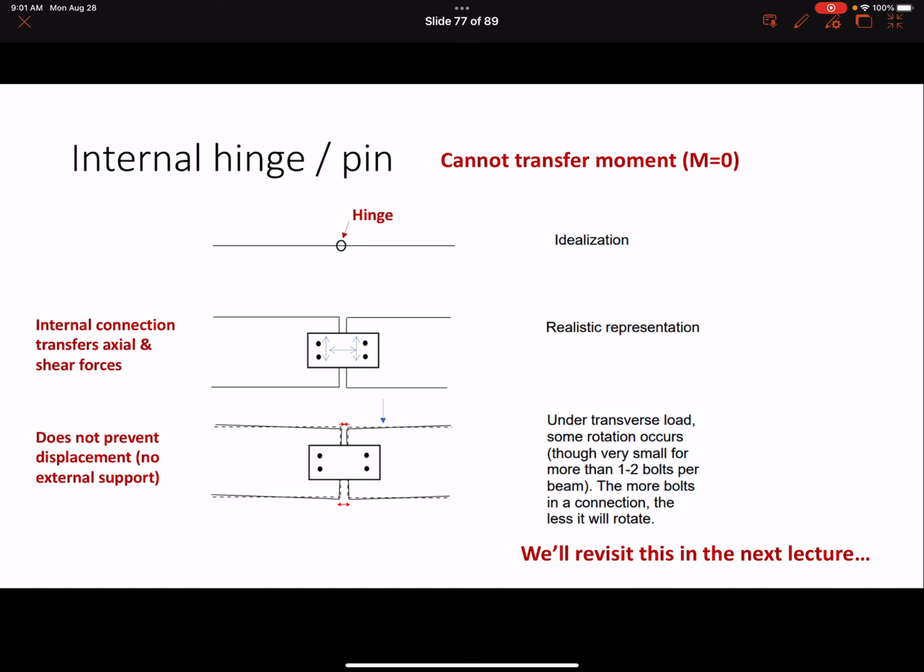All right. So last time we had just finished talking about different types of structural connections, right? So we looked at different configurations for roller supports, pin supports, and moment connections for steel, and we talked about reinforced concrete, and we talked about how wood connections are typically assumed to have pin behavior. And that's because it's very difficult to achieve full moment transfer with wood members.